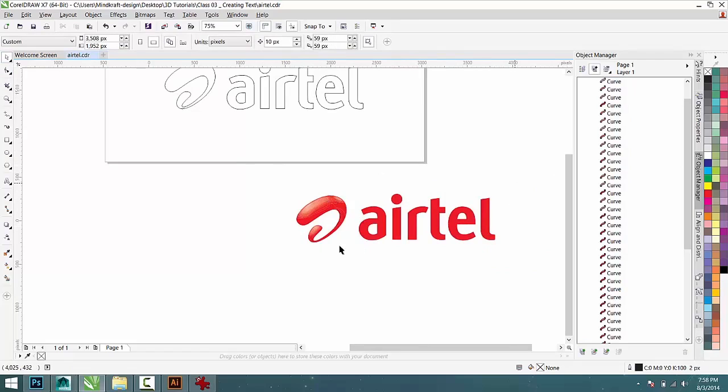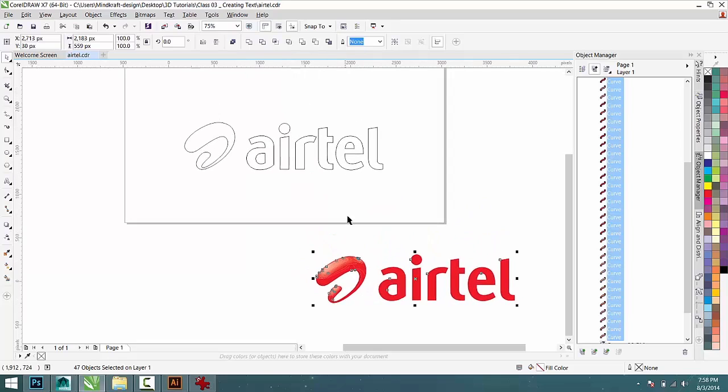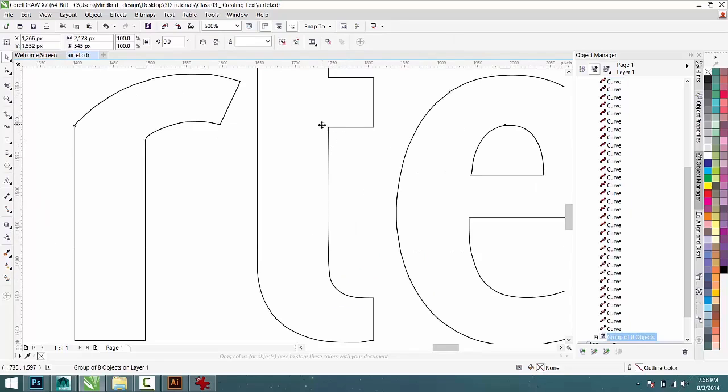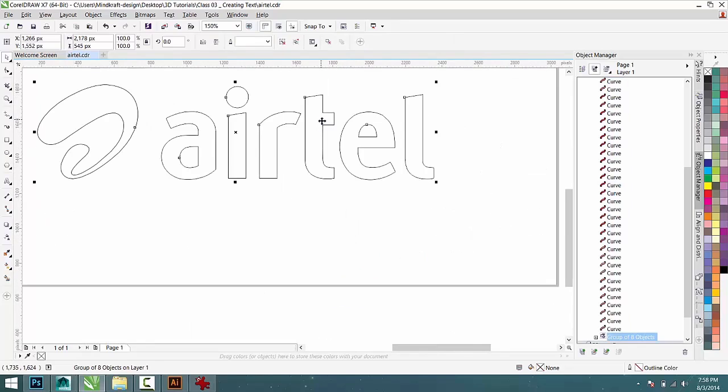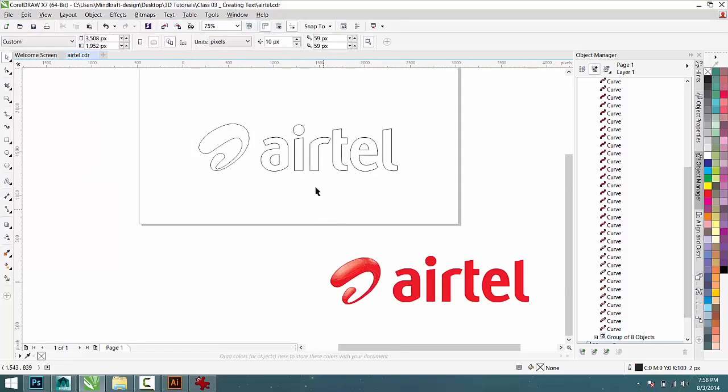So that is how I can get this. When I do this, usually you need the outline and not the whole object, because remember we are taking this outline back to Maya and using it as an outline for the shape that we want to create. Now, if you do this cleanly and you have clean lines during this process, it will make the process of creating curves out of these lines much easier when you bring it into Maya.